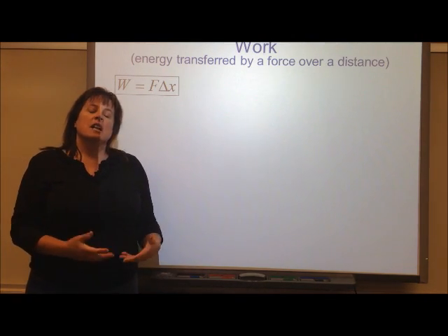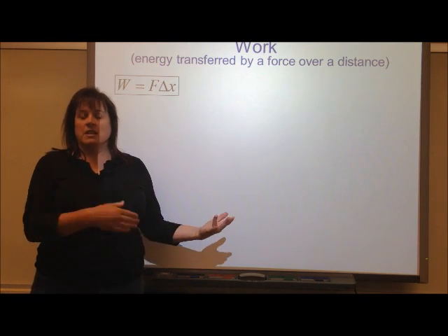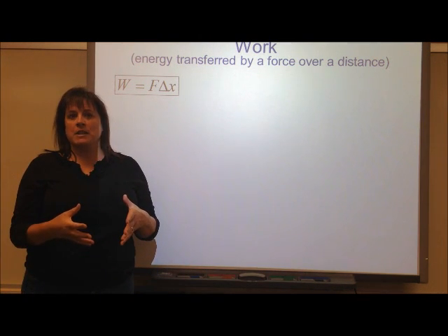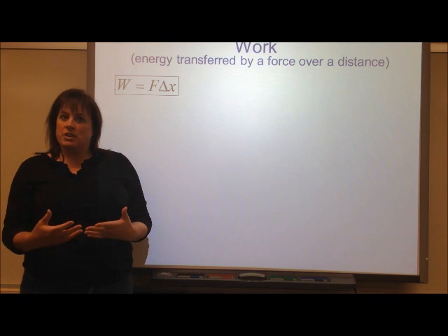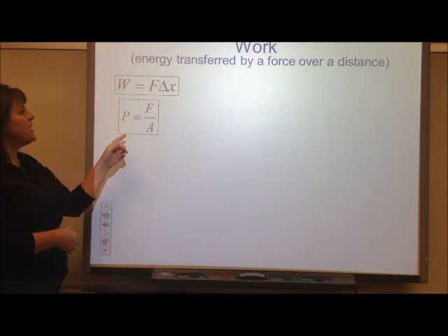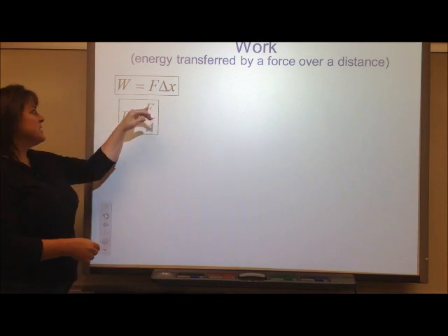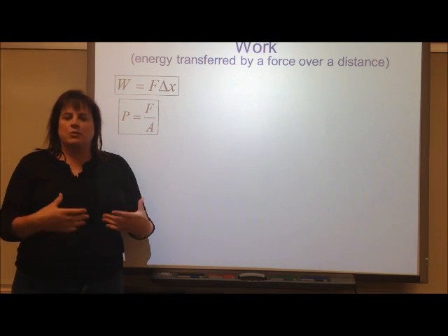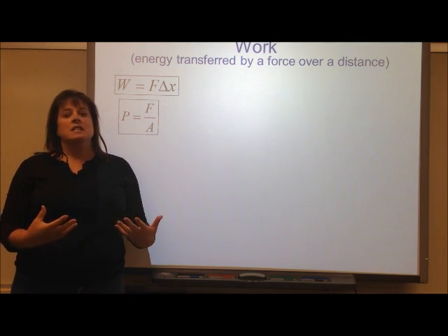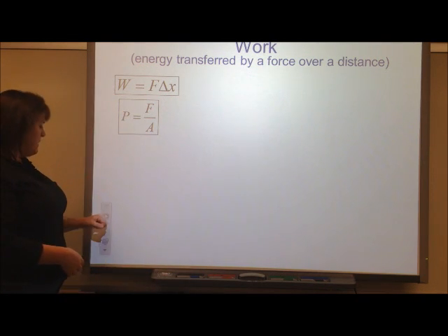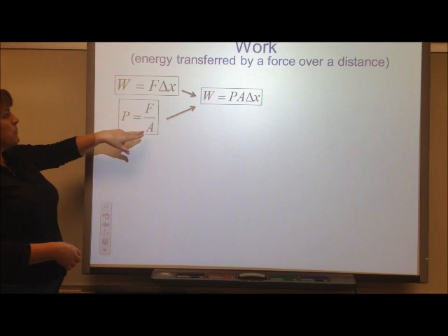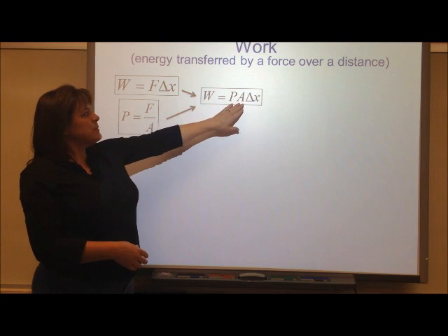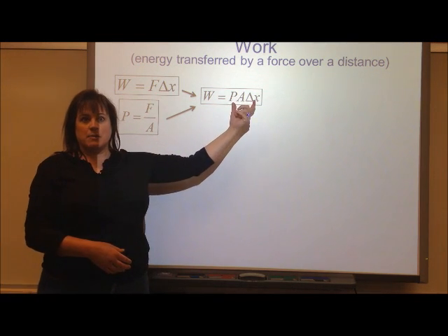Let's look in a little more detail at work and how we're going to calculate it in the thermodynamic unit. Work is force times distance. And if you remember back to fluids at the end of first semester, we related force and pressure to each other. We said that pressure is force per unit area, which means that force is equal to pressure times area. So when we're dealing especially with gases, and that's where we're moving now in thermodynamics, the internal energy of gases, if I substitute pressure times area in for force, we get work is pressure times area, and again, still have that displacement.